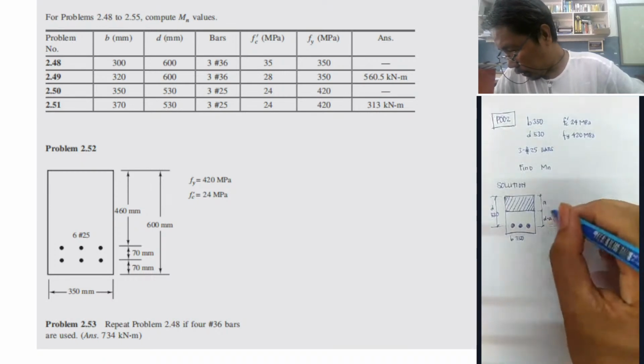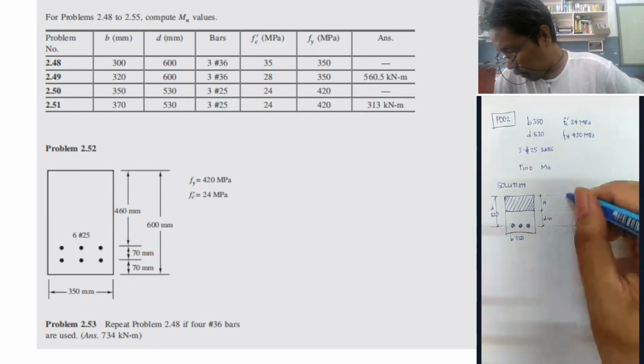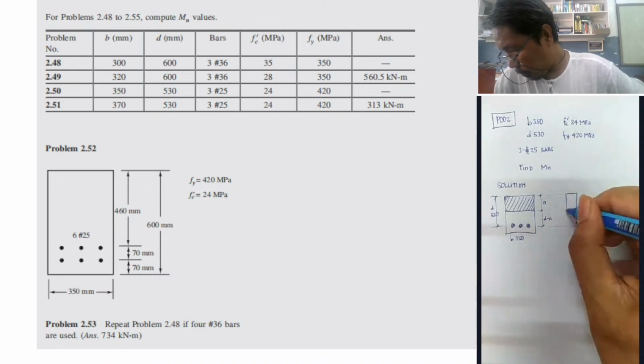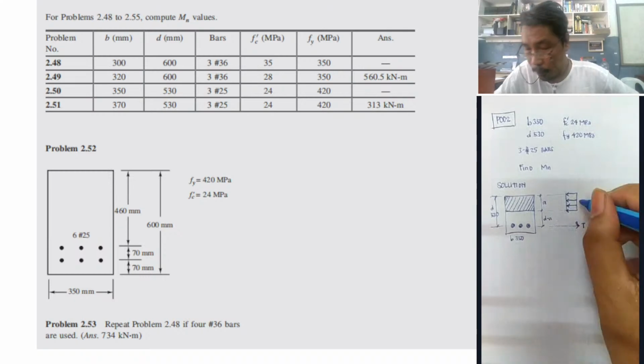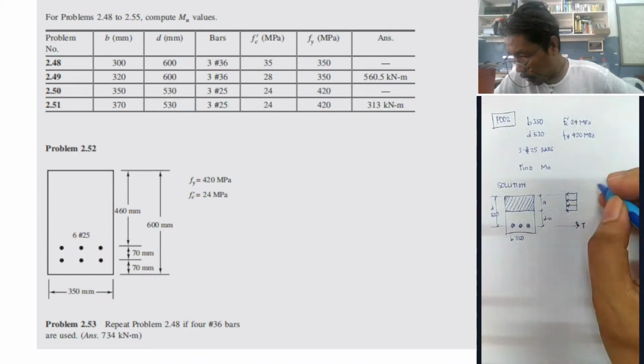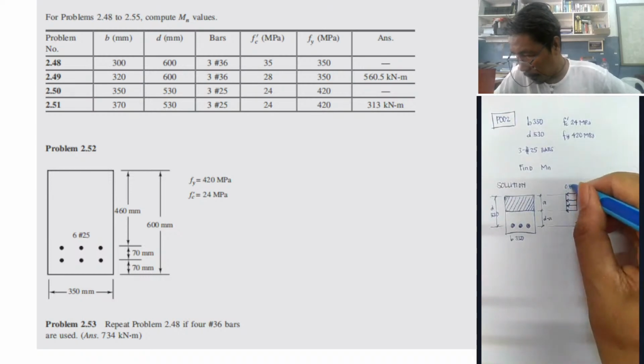What about this one? This will contribute a uniform compressive force that is equal to 0.85 FC prime.